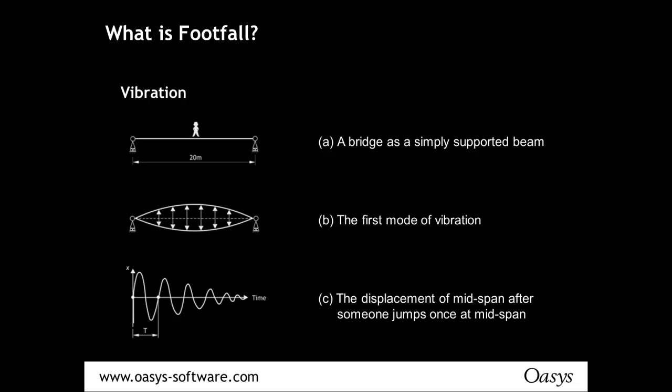Now, usually the thing to do in these cases is to work out the frequencies that the structure will vibrate at. A single beam is quite an easy calculation to work out the vibration of. When you're working on floor plates and so on, there's a lot more interaction. It's not an easy hand calculation, and therefore for things like floor plates, it's much better to analyze them using finite element analysis.